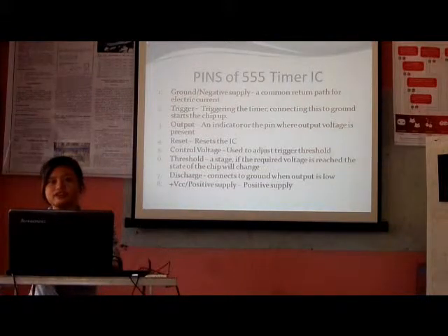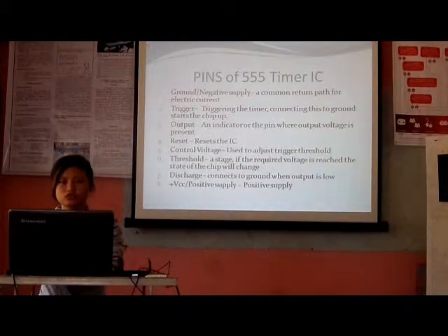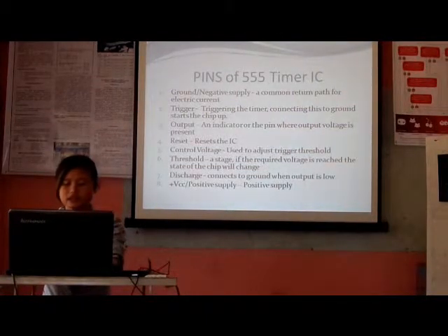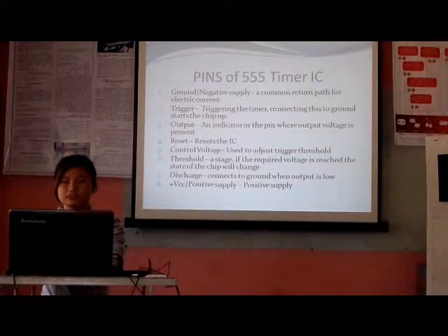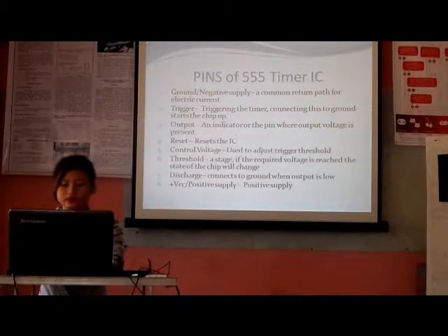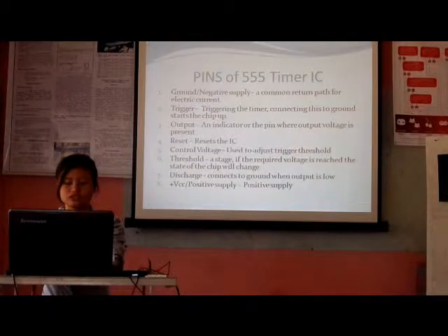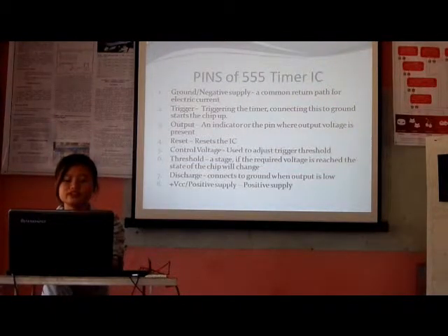The next pin of our 555 timer IC is called control voltage. The threshold and trigger levels are controlled using this pin. The pulse width of the output waveform is determined by connecting a POT or bringing in an external voltage to this pin.